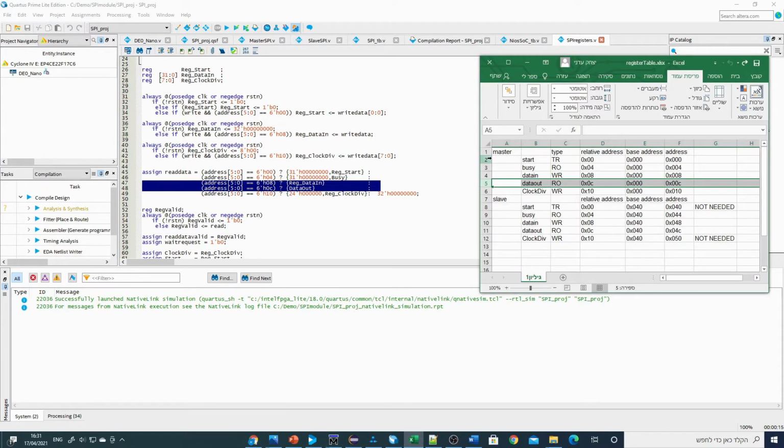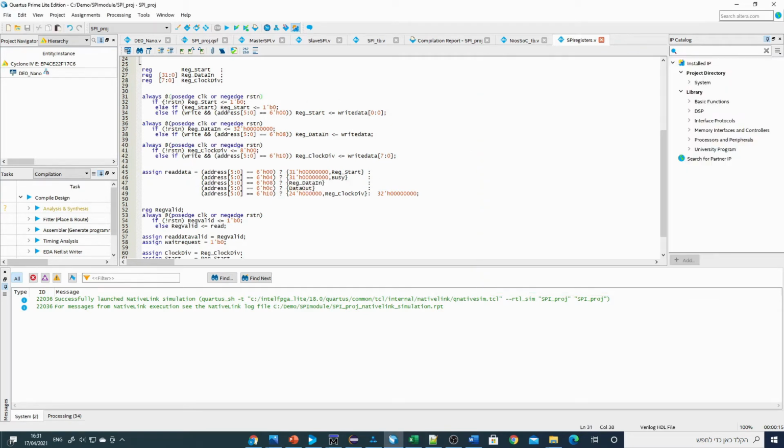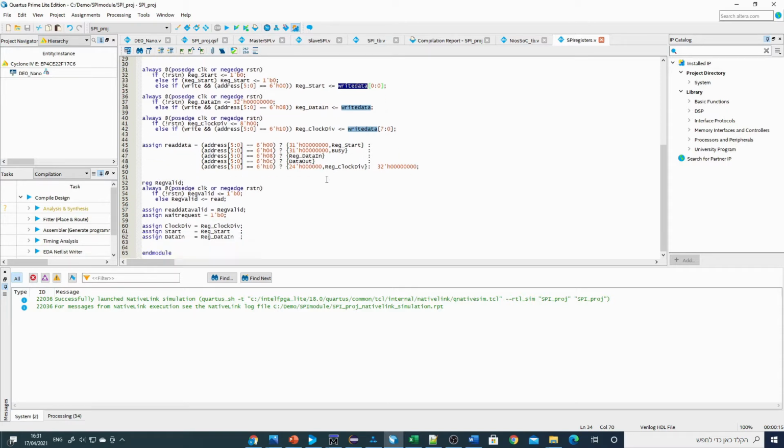The trigger register is a little trickier. It looks like the regular read-write register. It goes high, it goes low again. So the only time it goes high is when the write transaction itself is performed. We write it, it rises and it falls back again, and we have one cycle of transaction. That's it. We transfer the outputs from the register to the signals.